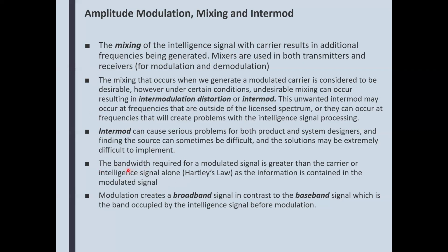Now, the bandwidth. The bandwidth required for a modulated signal is greater than the bandwidth of the carrier or the intelligence signal alone. Well, there's Hartley's law, Shannon-Hartley law. We'll come back to that. It has something to do with how much bandwidth we need to transmit the intelligence comfortably and at the same time ignore the noise comfortably. So it's a give and take kind of thing.